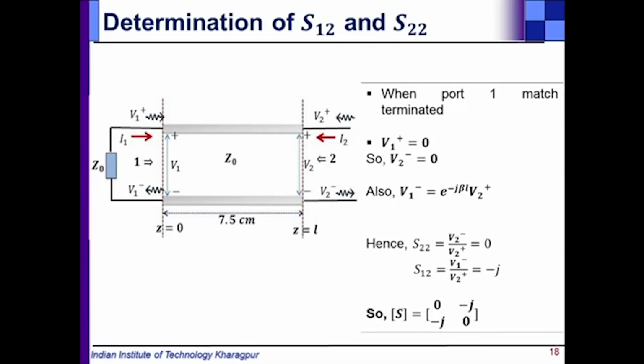But for a quarter wave line, both the forward wave or incident wave and the reflected wave are getting a phase change of minus j. If you want to avoid that minus j, you will have to change the line, so that you can get a non-quadrature response, but this is the scattering parameter. Now, if you were asked to find the Z parameter of that, you can use the formula we have given to go from S parameter to Z parameter, but directly evaluating the S parameter is easier, because this is a distributed line.